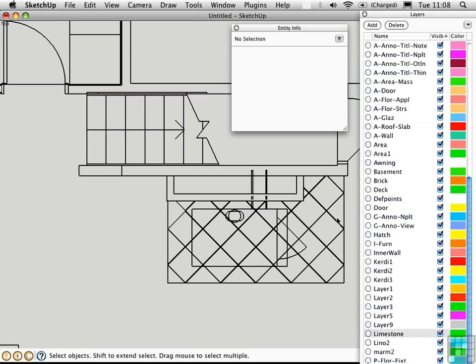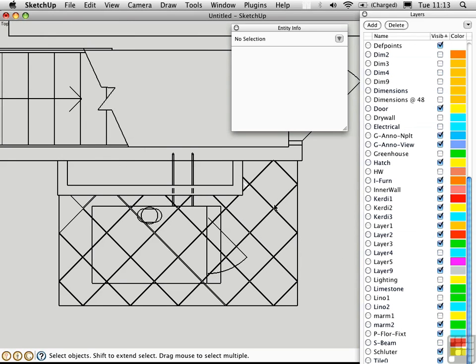In School B, which I'm going to call Let It Be, you can just leave all the CAD stuff alone and make it a group so that you can protect it. And then you go ahead and create your SketchUp geometry on top of that, so it's completely separate from the original CAD drawing. I'm gravitating more these days towards School B, and I'm finding it actually faster than trying to clean up everything in the messy CAD drawing. I'll show you both methods so you can choose for yourself.